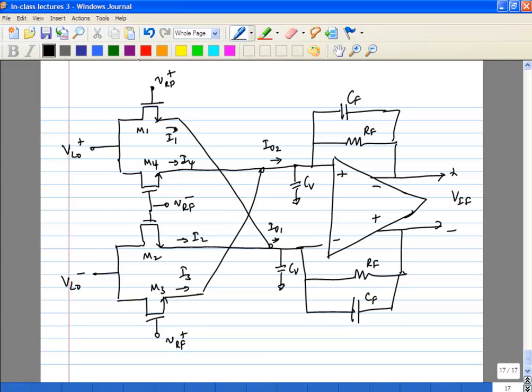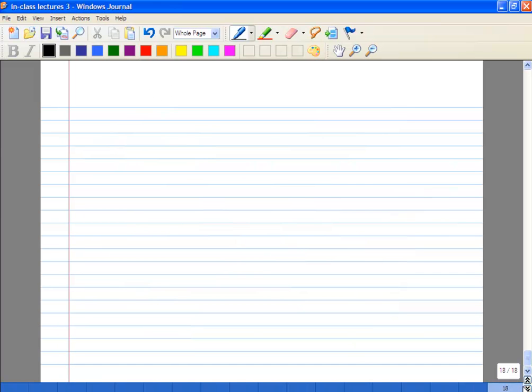So you are helping things along by adding these capacitors. They will create a signal ground, okay, at higher frequencies. And both CV and CF will give you some attenuation of high frequency components, because obviously since you are multiplying VRF and VLO, you are going to get LO plus RF, LO minus RF, you might get LO feed through terms. So you will get a bunch of terms, you are going to attenuate those using these 2 filters. It's a second order filter.